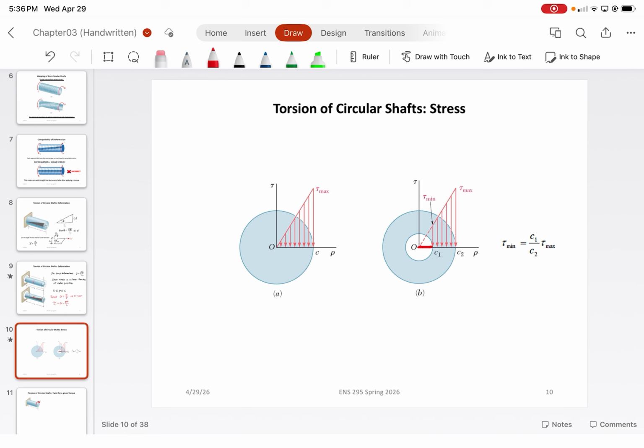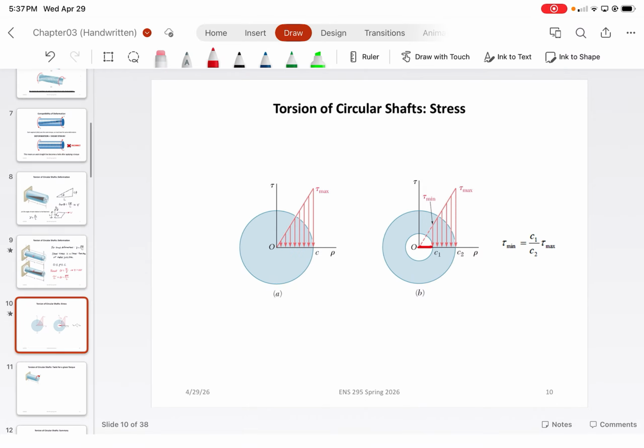All right. Now, as you can imagine, similar to how a reduction in cross-sectional area will increase the stress, we're technically reducing the geometric properties of this cross-section, so it's safe to assume that by having that hollow section, the stresses in general will be increased because it's now no longer a direct solid cross-section. Any questions about this so far? No?